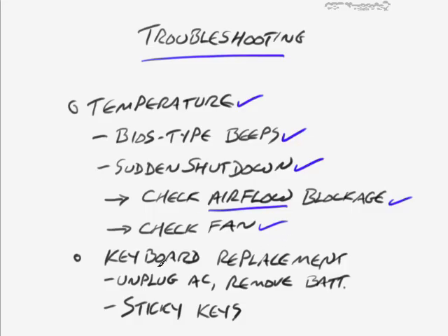Now, when it comes to the keyboard, if you do have to replace the keyboard, and I've done that more than a couple of times, then do keep these safety measures in mind. Number one, unplug the AC, not the air conditioner. Unplug the power, okay? This is not necessarily only a safety thing. Generally speaking, you're going to be safe in terms of not damaging the laptop. That's what I mean by safety here. Because you could accidentally touch something that's electrically charged and create a problem, or you could contribute to static problems as well. So unplug the AC, remove the battery, do all of that before you start to disassemble the case.